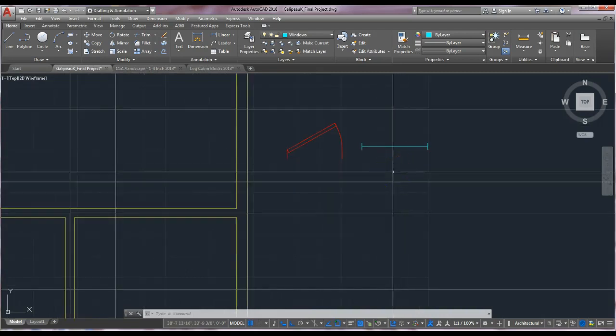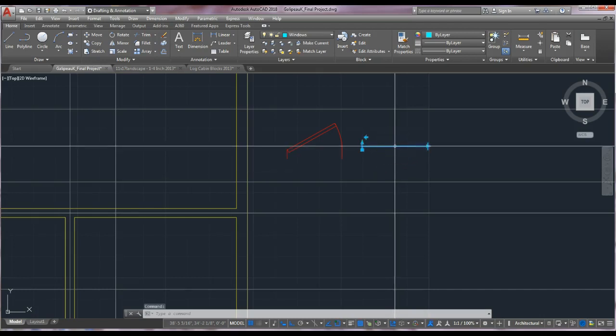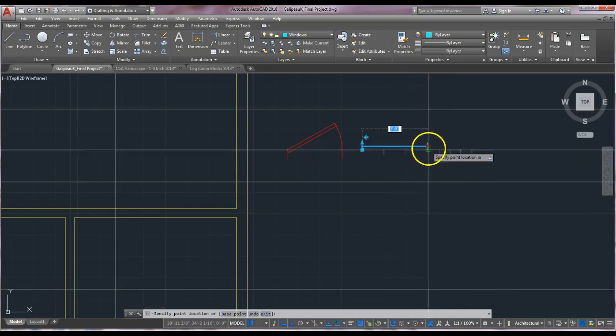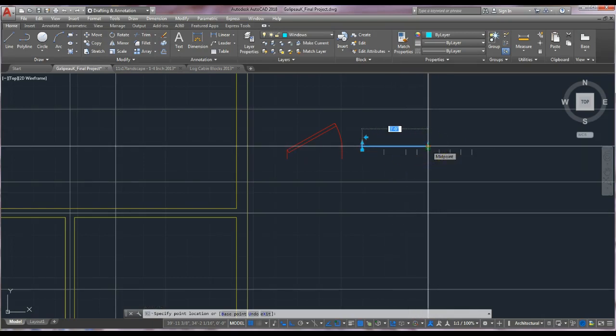If you notice on your floor plan, all of your windows are 36 inches wide. So if we have this dynamic block, we can select it. And if you grab this right hand arrow, you can see that these blocks, when we brought them in, were already 3 feet, 36 inches long or wide. You can actually adjust these to different sizes, and that's what's great about the dynamic blocks. But we can leave this one right at 3 feet.